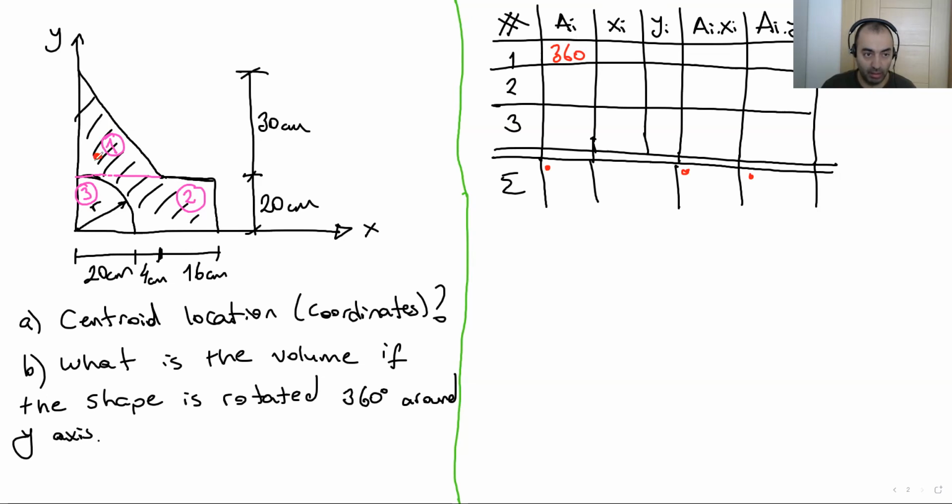Remember, it's going to be close to the highest point of the triangle. The 1/3 rule works again here. Total distance is 24, so this part is 8, this part is 16. So xi is 8. It's the same for the vertical direction, totally 30. Divided by 3, this part is 10, 10, 20. So totally from here to here, 30.